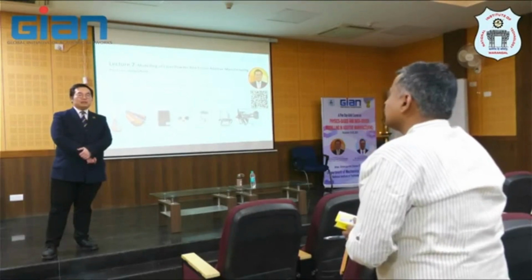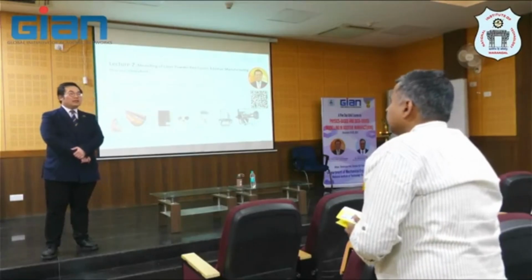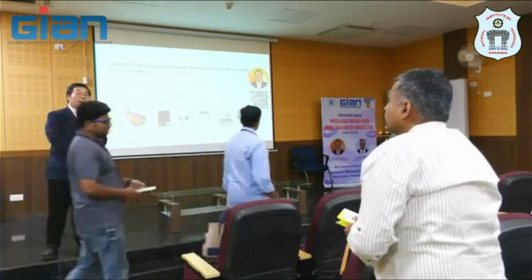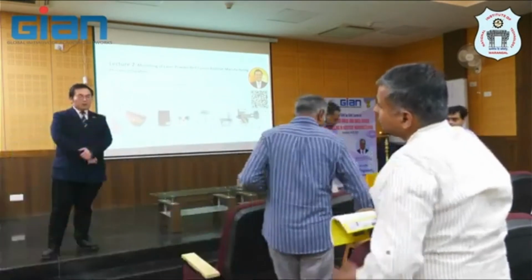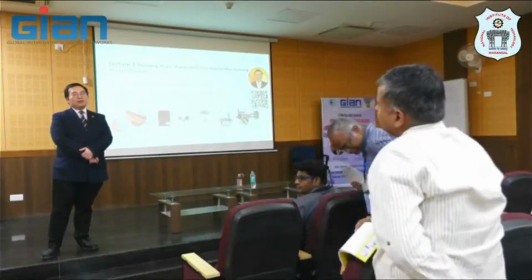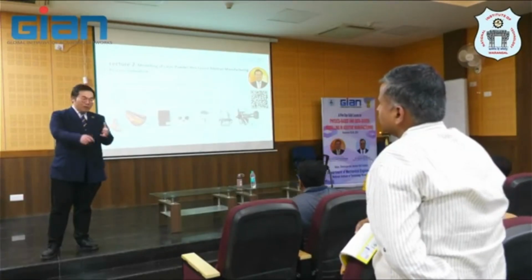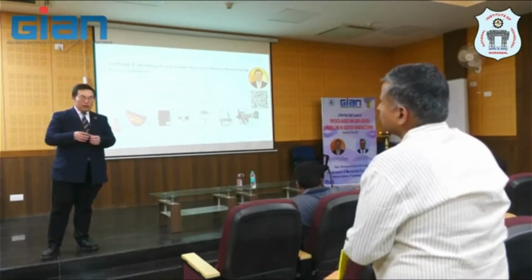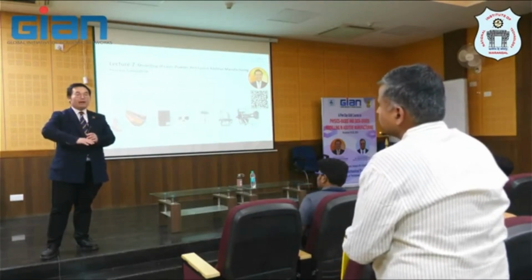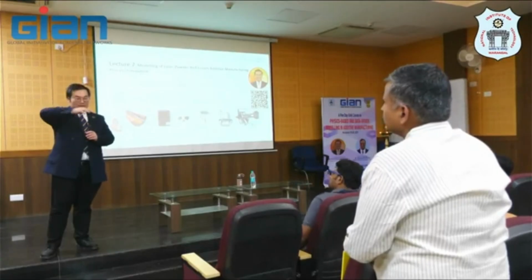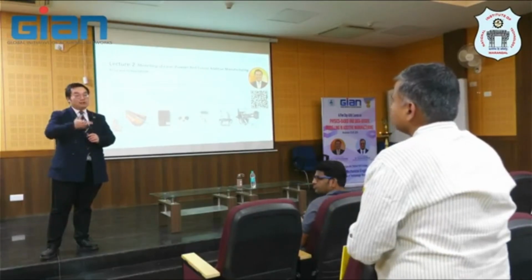The reason we use investment casting is because we want to remove the grain boundary, which decreases the creep life of the material by about 3 times, right? But you're asking about if you use additive. At the moment, with powder-based fusion, I think it's probably difficult to control the thermal gradients. In investment casting, we introduce a grain selector, so we control the planar thermal gradient across the geometry. And then you grow only 1 grain, right?